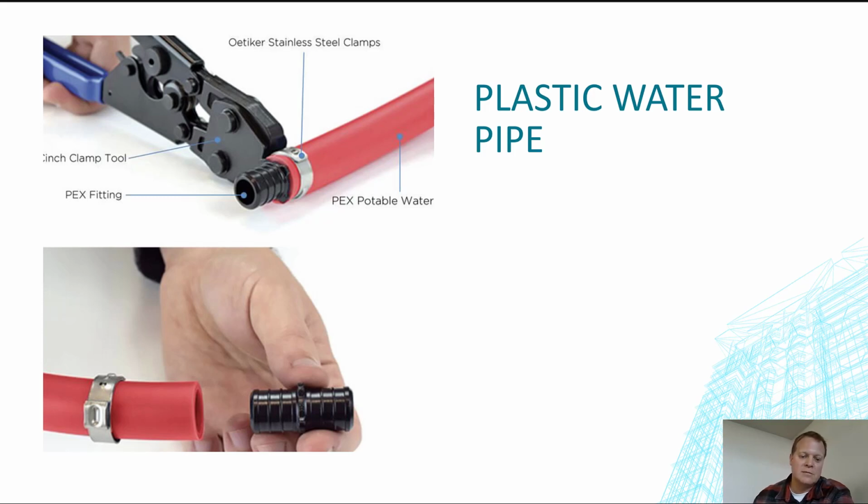It expands and contracts. So in hot water, you're supposed to add a little loop before you make a 90 or go somewhere else. You're supposed to add some more. So you're not supposed to do this very tight. Is kind of the point. So that's one material method of moving water around, and these come in different sizes, different size pipes, but usually